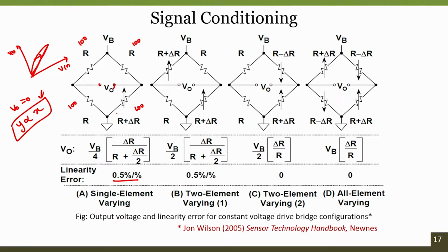So now, under no loading condition with all the resistances the same, V0 is 0, good. Then for any change of resistance, because this is the only sensor, for any 10% change of resistance, if I observe the output variation to be some y%, and that y% is constant throughout the operation, I can say this is linear. Now, 100 ohms into 10% is 10 ohms.